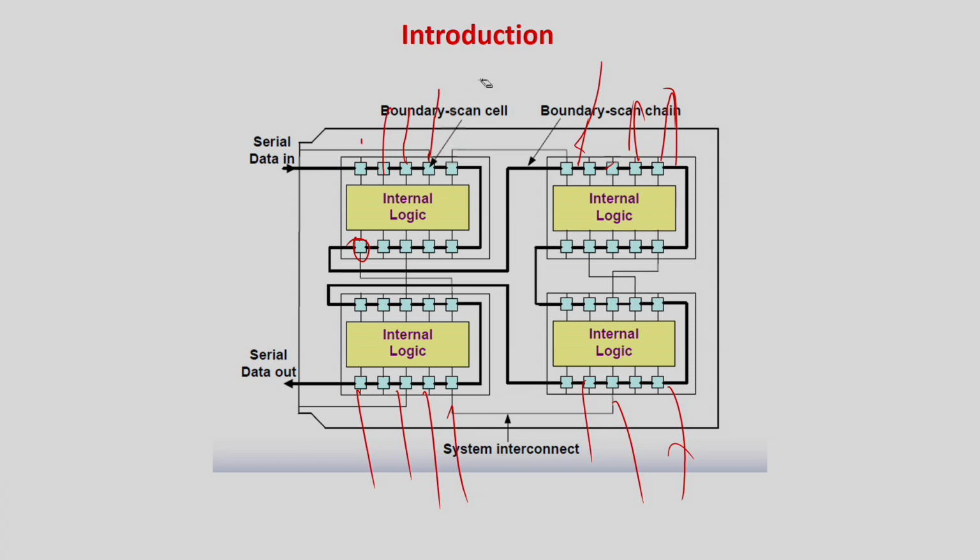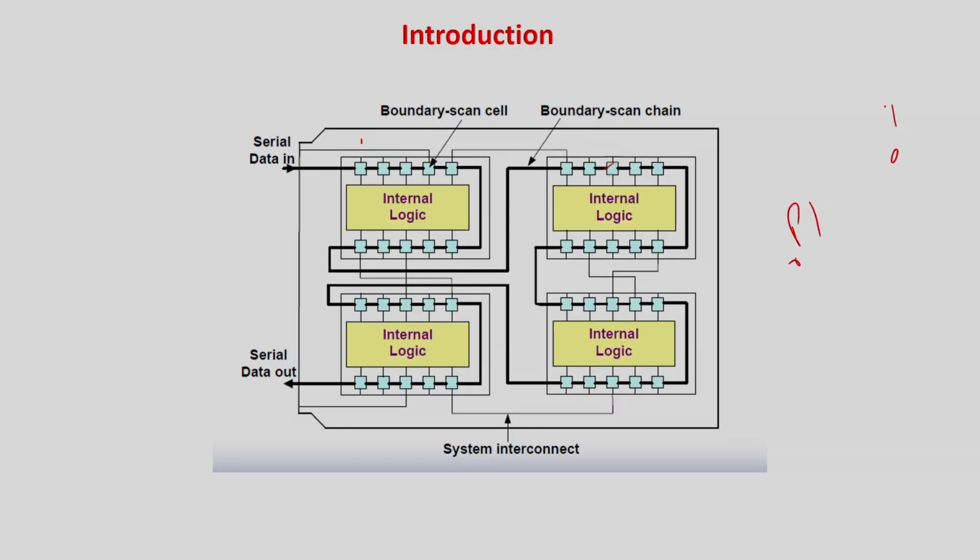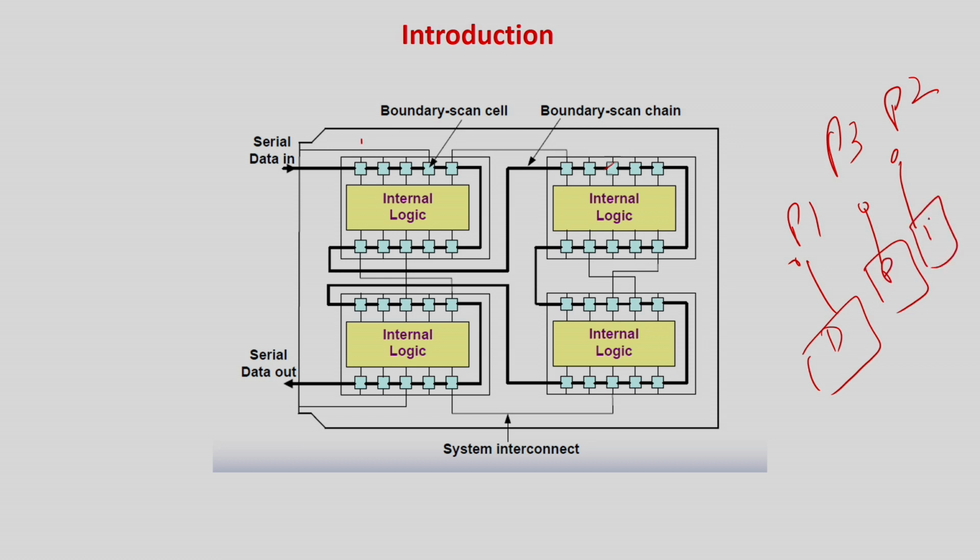As you already know, scan chain means some of the flip-flops are made into a single shift register, and whatever pattern you want to apply, you set it accordingly by the scan shift. Once the flip-flops have got those values, you can again go to the normal operating mode and test it, and again capture the response in the scan chain and bring it out. The simple idea is that multiple points in the circuit have to get these values which are fed by different flip-flops. So say for example point 1, then point 2, like that, a lot of points are over here, point 3, these points are there, and these are all connected by D flip-flops. These are the D flip-flops and these are the D flip-flops, right?